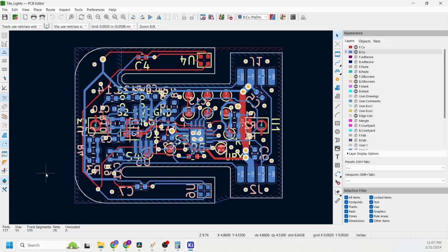I also made sure that the traces and copper fill were only on one side of the arms where they're going to flex. This will help them bend easier, since I don't need to stretch or compress the copper on both sides of the board to bend the arms. So I put the order in for the circuit boards. Now there's nothing to do but wait.